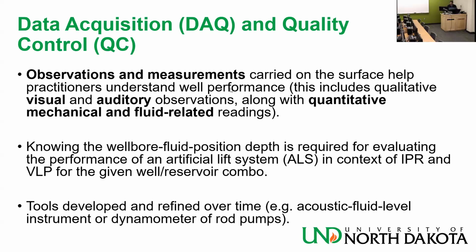Also, what rates can we deliver? Because I don't want to put my well on ESP, electric submersible pump, which is something very important, very expensive, and very difficult to maintain and fix if it has problems. And then the well will be producing very small rates, and then I would be saying, oh, I wish I had put it on a pump jack, which is much more common and cheap and easy to fix, especially onshore.